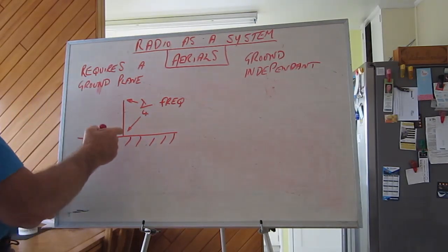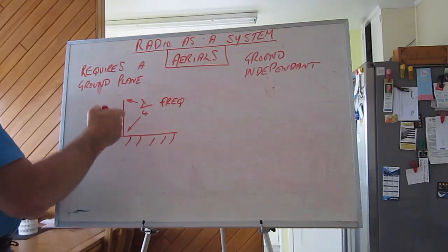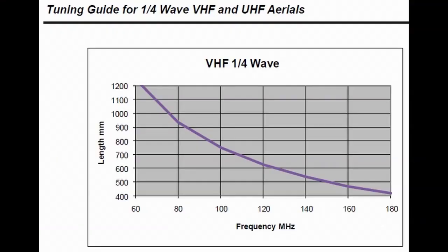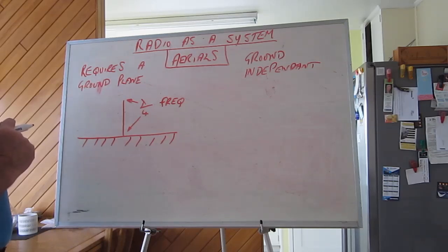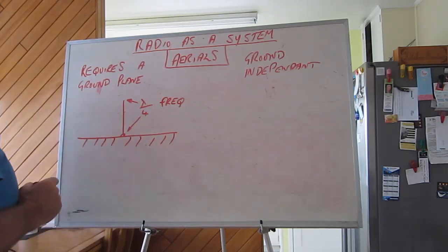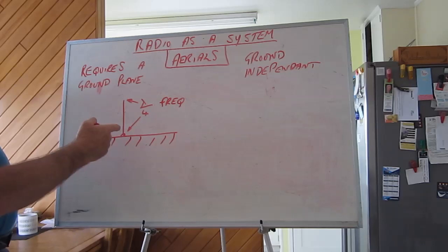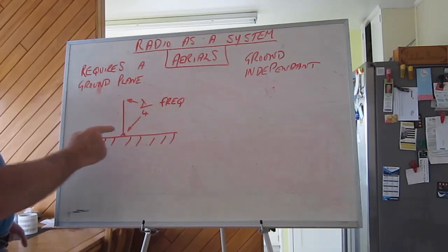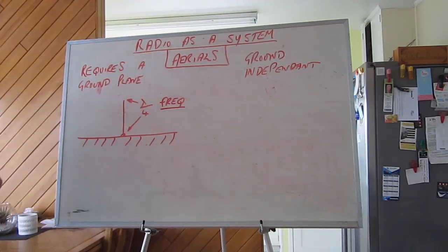If you do not trim this antenna to length determined by the frequency, then that won't work properly. It's a fairly fundamental thing. You can't simply take a whip antenna out of the store and bolt it on something. It won't work. The length of this antenna, you have to look up a chart that will give you a physical height in either inches or millimeters, dependent on the frequency you wish this antenna to operate at.